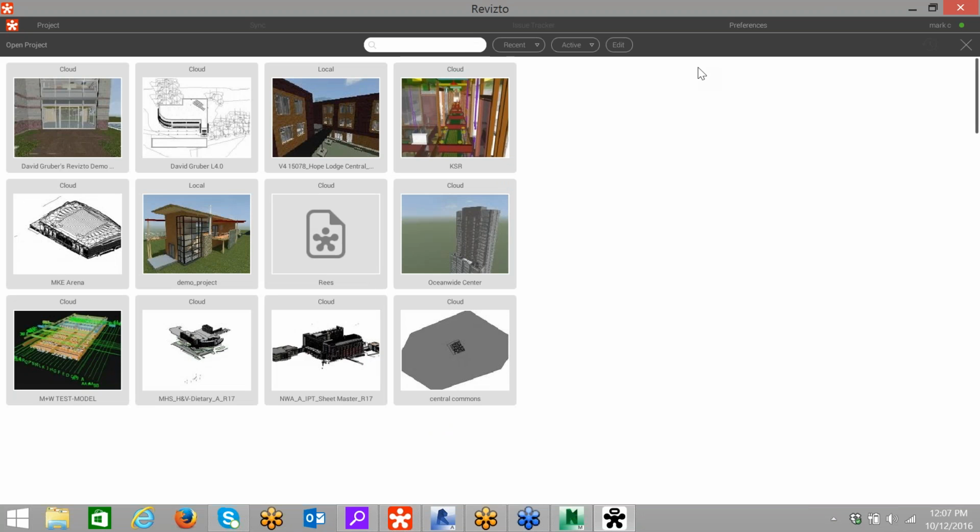So what that means is that if you're utilizing a very large project, you need to find where that ideal middle ground is. So for customers that are exporting maybe a large hospital project that has a lot of details, maybe a large project that's going to have a lot of polygons, what we've seen happen is they'll export the first floor and the second floor and the third floor all as separate projects. So here we'd see floor 1, floor 2, and floor 3. And by doing that, we're greatly reducing the polygons for that entire project and only pushing out what we need to walk through in VR. This will greatly reduce the amount of polygons in each project, and it will increase the frame rate in your Oculus or Vive for that matter.